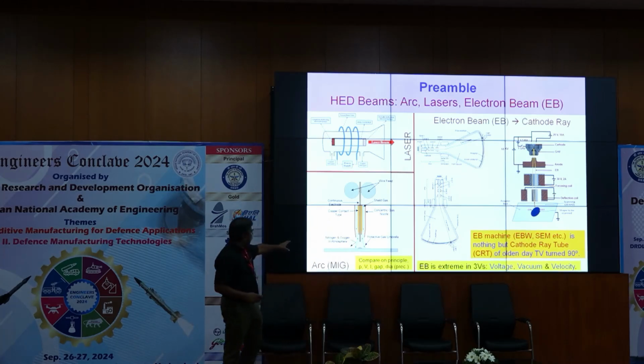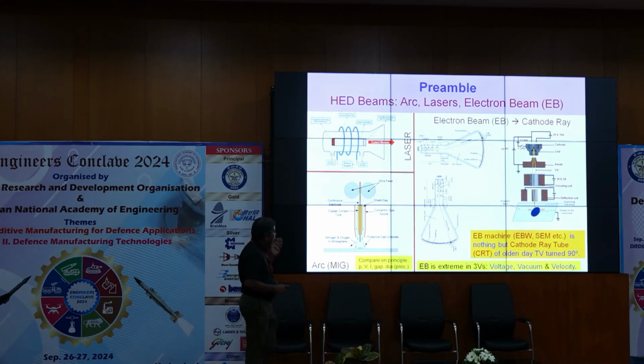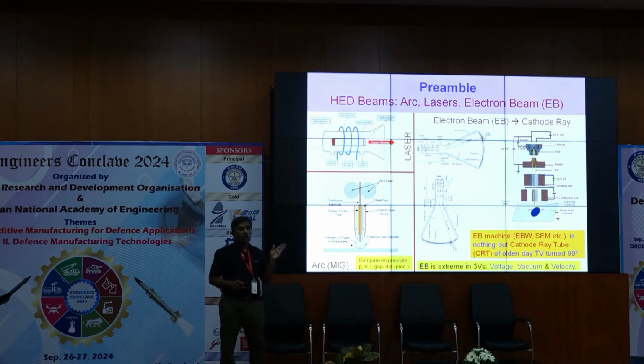So here, as you know, it's a low voltage, high current system. You approximate about 100 volt will be the welding voltage for the arc, whereas the current would be anywhere from 400 to 1200, 1500 ampere. Whereas there, since the voltage is very high, if our machine is 12 kilowatt, we will have only 200 milliamperes of current. So this is a low voltage, high current system. That is a high voltage, low current system.